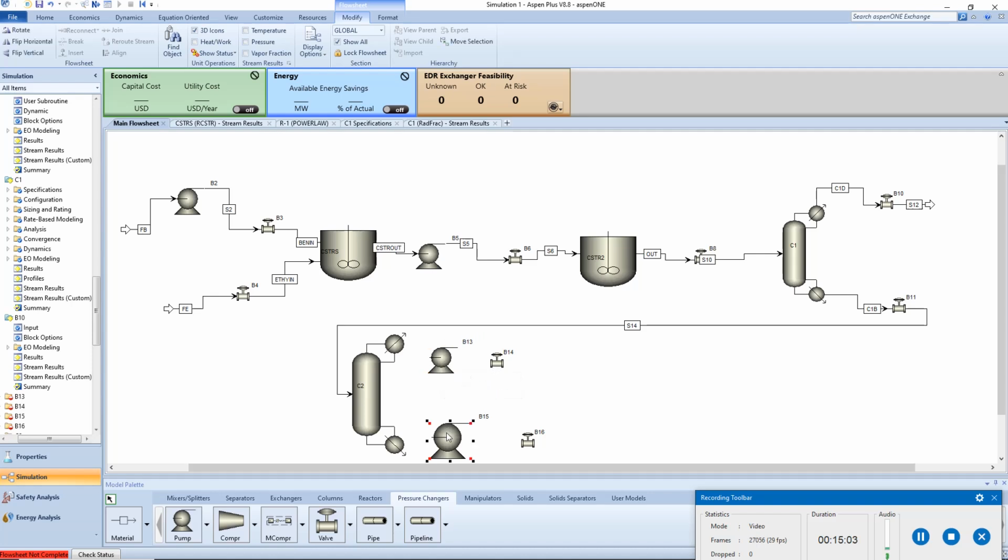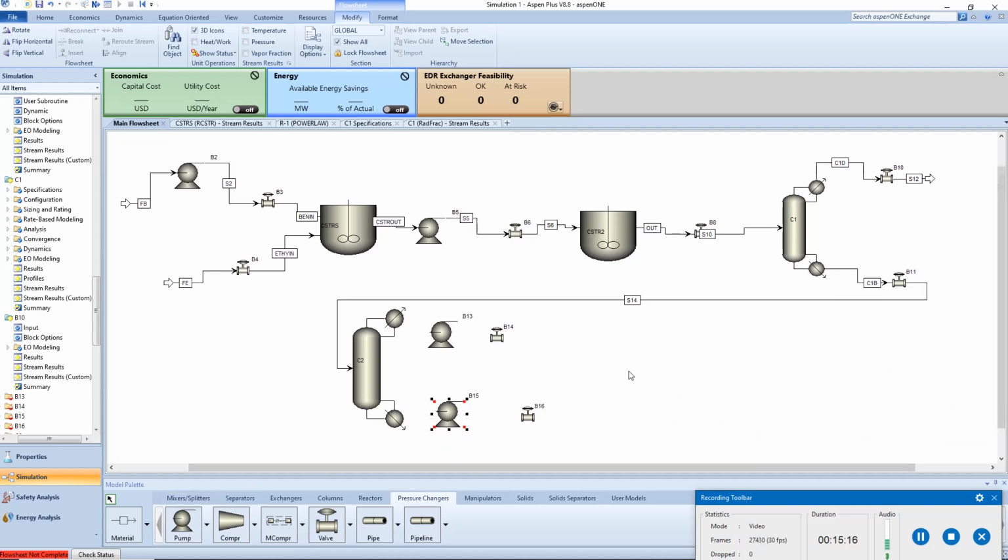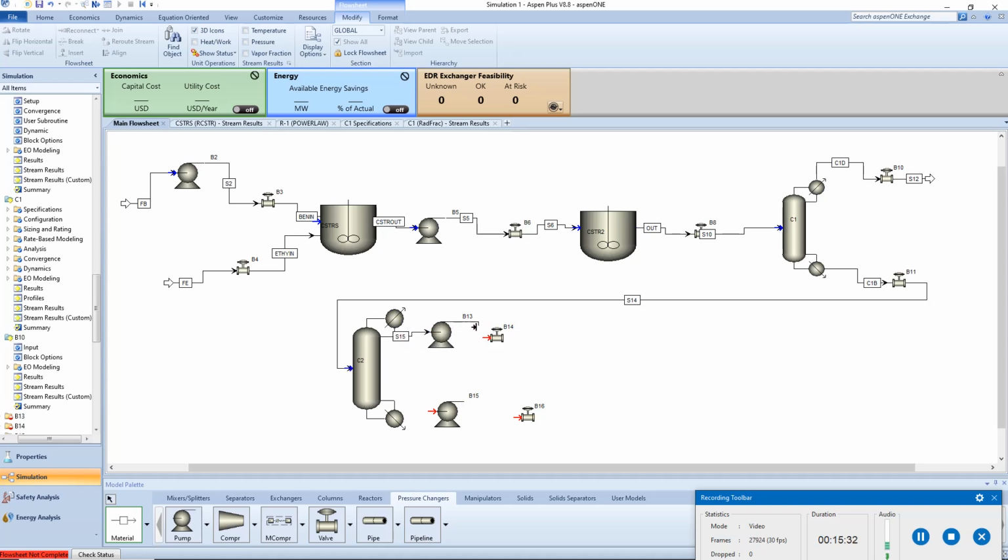The pump and valve arrangement is necessary for all the columns for the pressure, and the valve is necessary for the steady state degree of freedom. Since every column has two steady state degrees of freedom, there should be two valves at the outlet of each column, and according to the pressure requirement downstream, a pump may or may not be required.